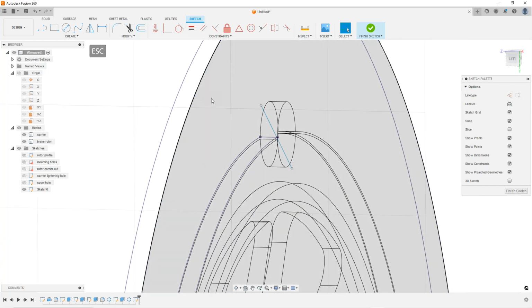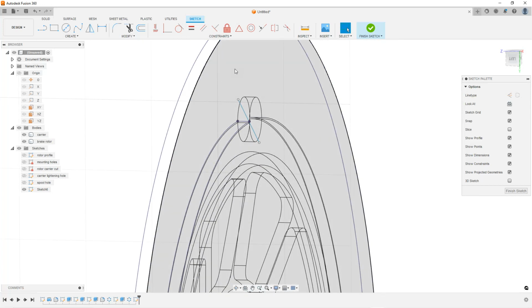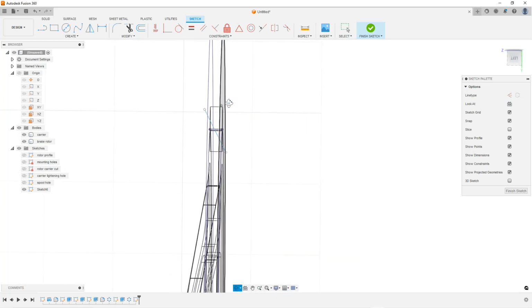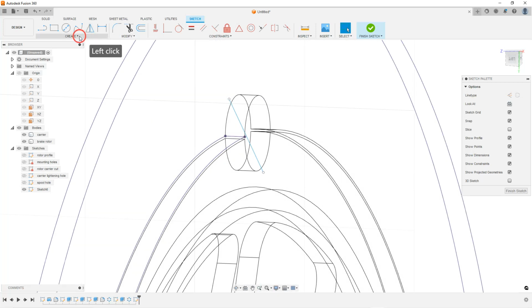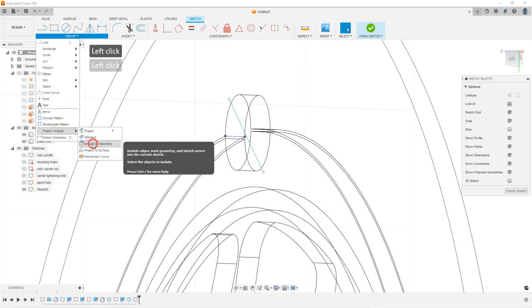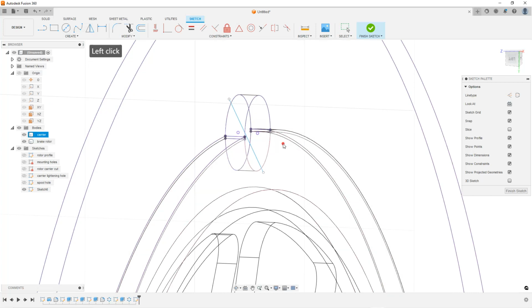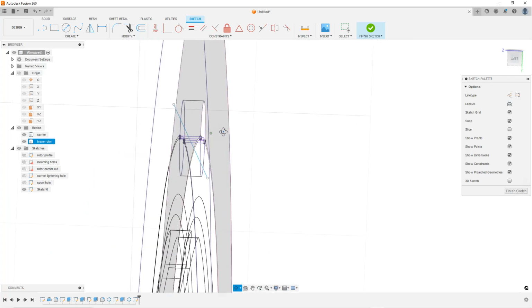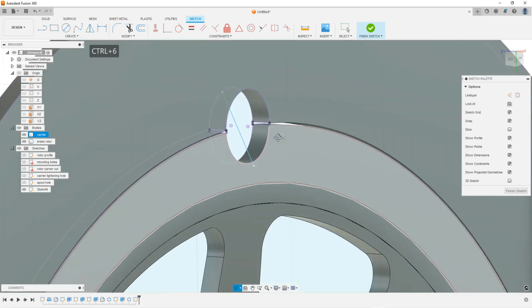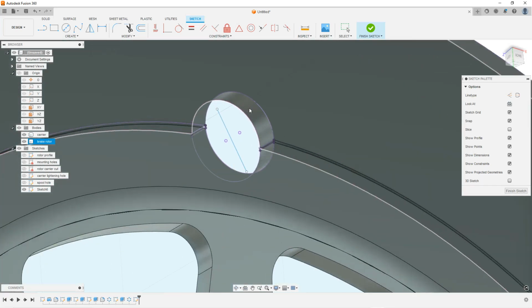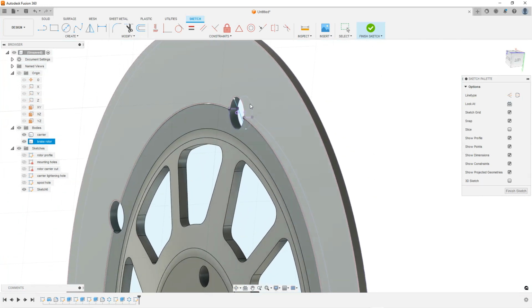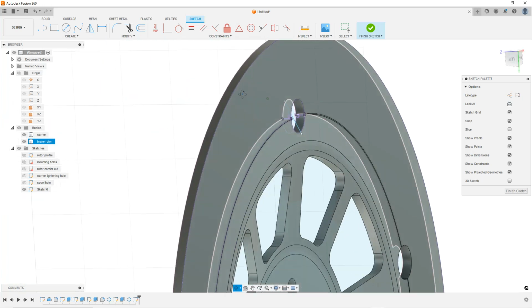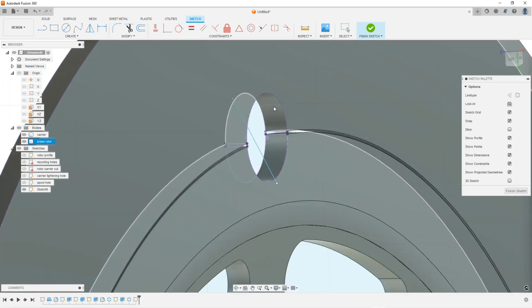So I included the 3D geometry that was, I guess, this face and this face. So that's not actually what I wanted. So when I include the 3D geometry, I've got to pick that surface right there. So let me go back to shaded mode. What I did the first time is I picked this surface, and it gave me all the edges of that surface, except for the ones that I wanted.